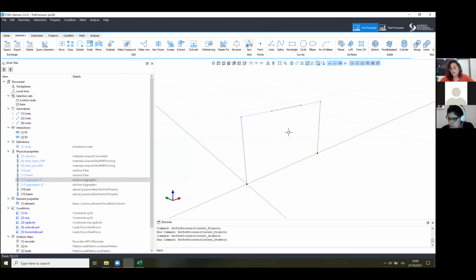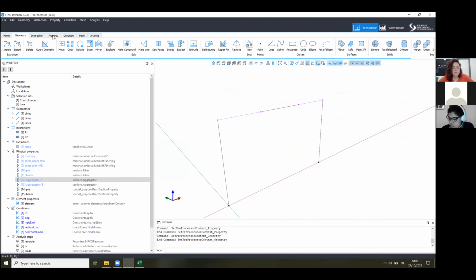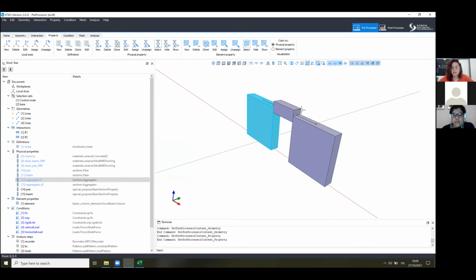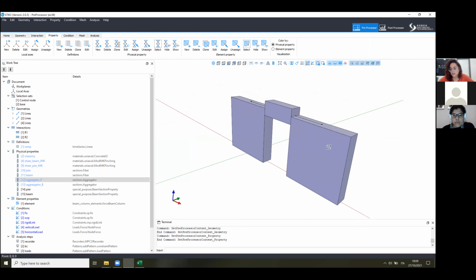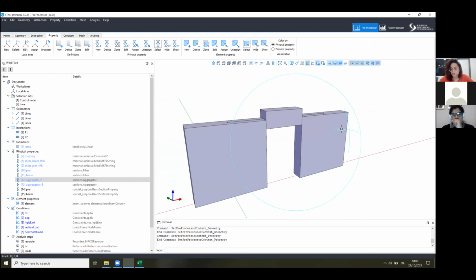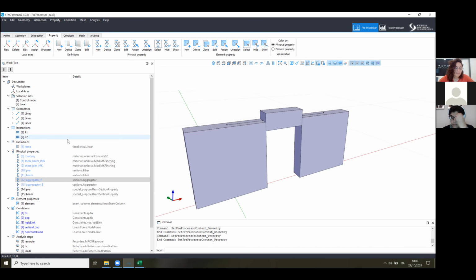Just taking a step back, I'm sure you know, but the idea of equivalent frame modeling is to simplify a massive structure made of masonry by identifying specific piers, spandrels, and rigid joint elements in a facade. Let's say this is not a facade, but whatever Masonry wall you have, you may have this kind of distribution and differentiation of the elements. This is because, very simplistically, damage has been observed to happen mostly in piers and spandrels in these kinds of structures, and so the connections in between these elements can be assumed rigid.